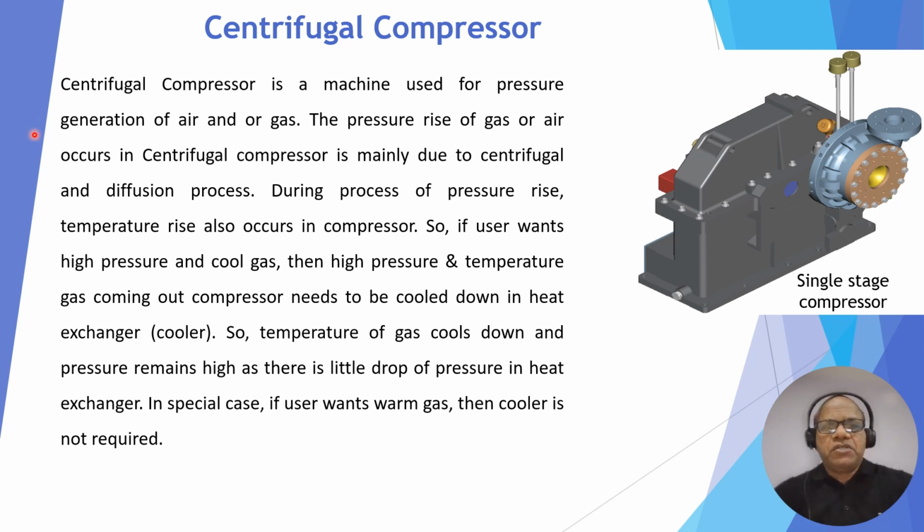The pressure rise of gas or air that occurs in a centrifugal compressor is mainly due to centrifugal action and the diffusion process. Centrifugal action means the wheel, the impeller, is rotating, and because of this, the gas is also rotating, which creates centrifugal action. Diffusion has two processes.